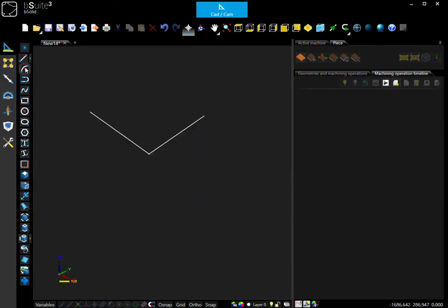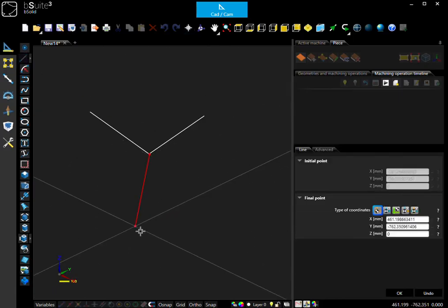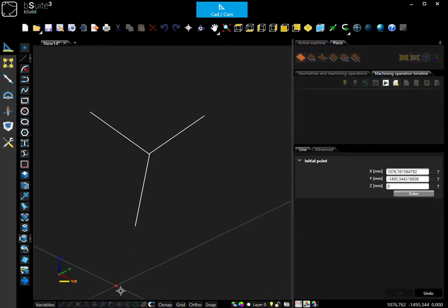Next to the variables, you've got your object snaps. So I can snap to endpoint. Really good for creating accurate geometry. And with each drawing operation, you can select a different one. So find the midpoint there, and off I go. Or you can set up some defaults in here too. So I've got that defaulted to the end, mid, and a few other bits and pieces. Go OK, and it'll automatically default to those when I've got this turned on.